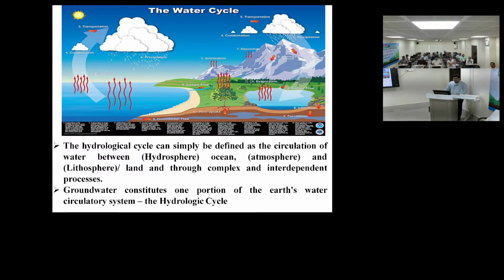So once it forms the rain on earth's surface, we should know what the capacity is, because most of it goes into surface runoff, and about 30% we call the infiltration of the soil. So ultimately infiltration is the factor by which we recharge the groundwater. In terms of source certainty, this is a very important factor, because rainfall doesn't contribute the whole 100%. There is surface runoff, there will be infiltration, and from the infiltration, there will be base flow.